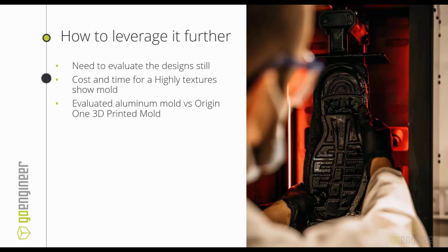There's not a whole bunch of excess breakaway bar support you have to deal with. It's a very easy thing to clean up and take off the tray and go from when it finishes printing to a useful part in a matter of a couple minutes, to rinse it and give it a quick 5-10 minute UV cure. So lots of benefits on that for the post-processing side.